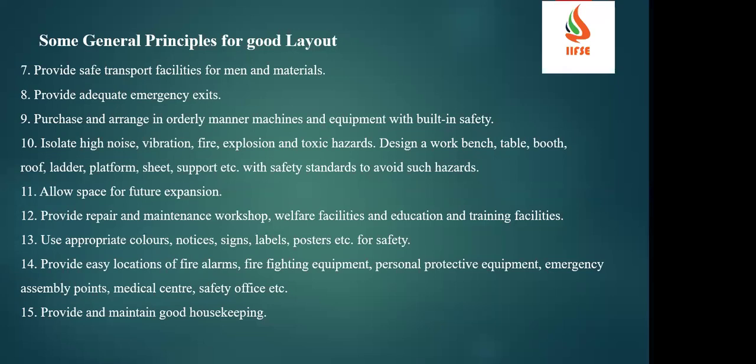And isolate the high noise, vibration, fire, explosion, and toxic hazards by design. So by way of segregation, by way of built-in safety, by way of explosion-proof or fire doors, leak detection systems, and for noise isolation, acoustic enclosures you are keeping, etc. And allow space for future expansion if you have a plan. Then provide a repair and maintenance workshop, welfare facilities, and education and training.